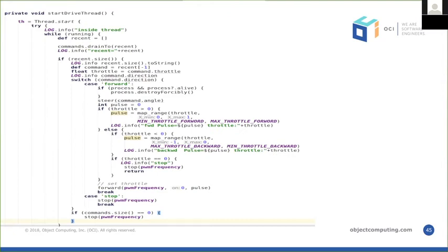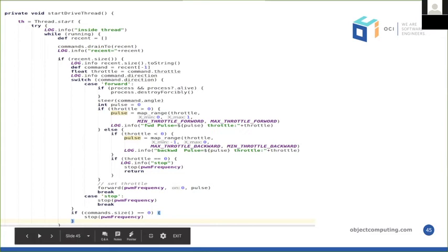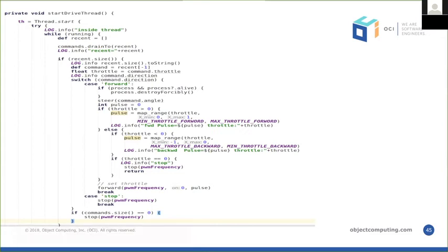And then we try to figure out what that range is so we can translate that to a pulse width modulation value. Those are simple numbers of gradients, and we can convert that to a pulse. And then we send that pulse to the car saying, go forward or go stop. We're actually using forward for both because the pulse width value for backwards is just a different range of values than forward. The motor doesn't have a concept of going backwards per se, when you're communicating with it with pulse width modulation.